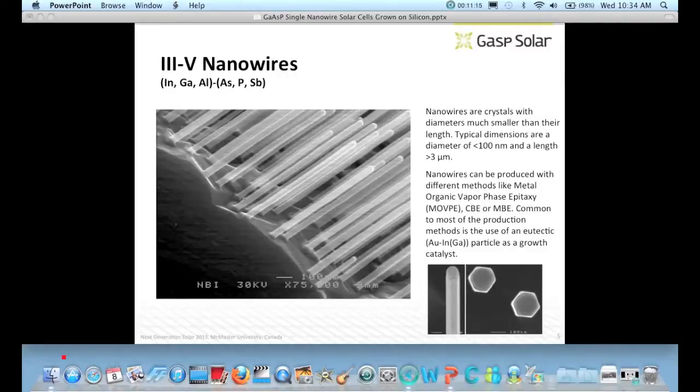These nanowires are microns long, nanometers thin, and it's difficult to see in this image, but they actually all end with a gold catalyst particle. Now, this is non-lattice-matched growth. These are indium arsenide nanowires, and they're grown on a gallium arsenide substrate. There's a 6% difference in lattice matching. It's possible with nanowires because they have such a small diameter. Now, the diameter of nanowires is controlled by the growth catalyst, and they have a hexagonal shape, if you see here directly from above.